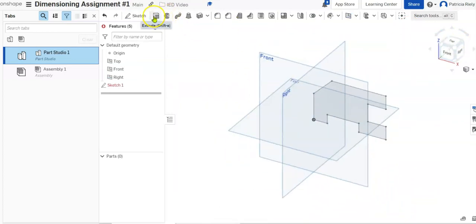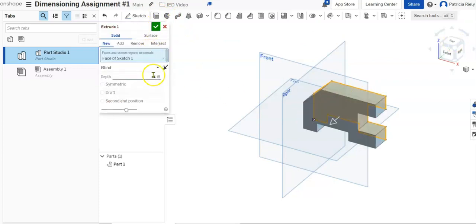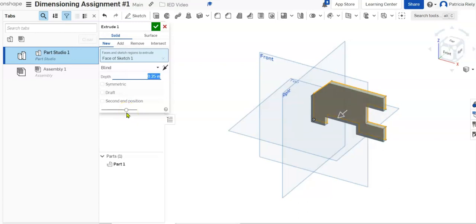And I'm going to extrude it, and looking at my directions, it says to do that a distance. So tell it what you're going to extrude. And you're going to just do a distance of 0.25 and hit enter. Okay, that's your first part. Now, I want this part not to be called part 1. Okay, oh yeah, I have to just hit check.